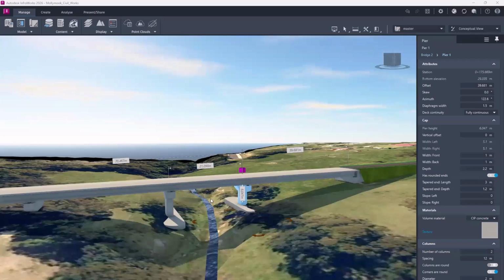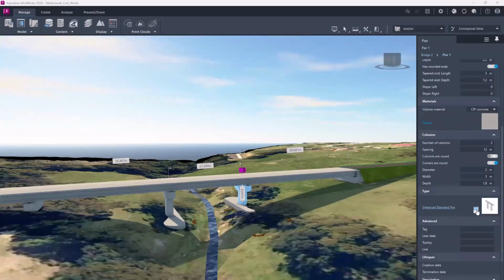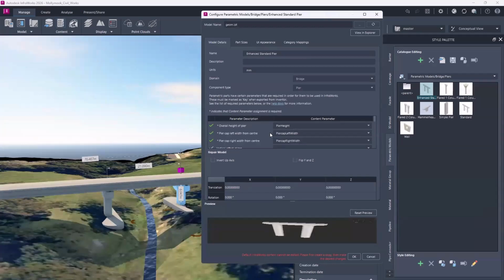Now, if you're wanting to see those vertical pier information, it's down here. So I've got the pier type. There's a properties panel here. And when I open that up, it is this match by surface to bearing. So if you set that one, then you'll get that vertical pier placement.